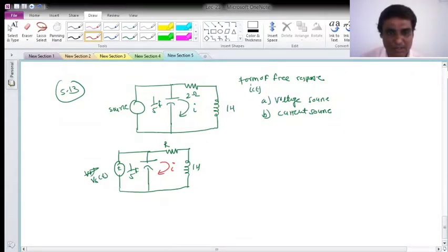the voltage source is connected across the capacitor, so this capacitor is ineffective, right? How many independent initial conditions can I set? Only one, that is the initial current through the inductor. It consists of only one independent initial condition, that's why the order is 1 here. And this is the reason I am taking this example.